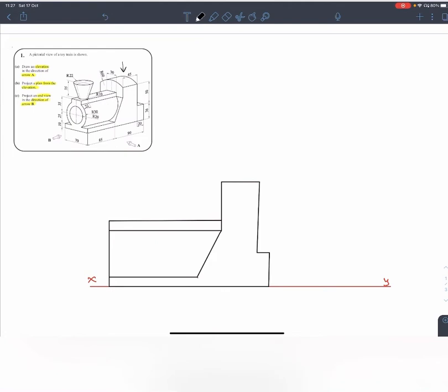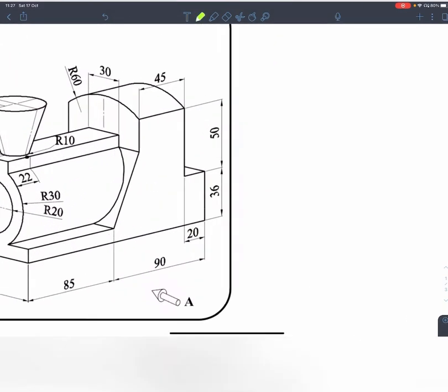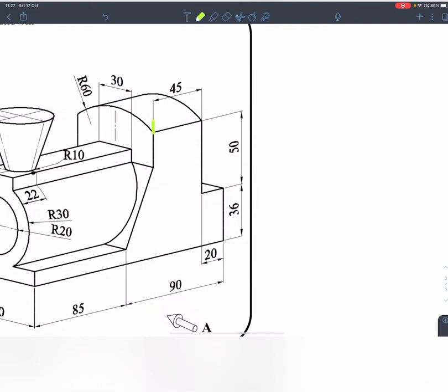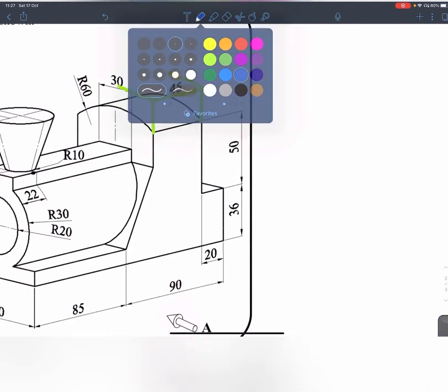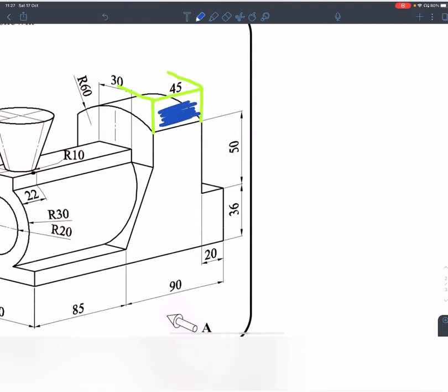So if we look at this section here, we see that it's curved around this way, right? But if we're looking in at it from A, if we follow our box like I've been showing you in the previous lessons, if we follow the box up, I'll do it in green, I'll zoom in here, right? If we follow the box up and around this way and down, the box should come along this way to meet the 30, right? So if I color in that surface, like I've been doing in the previous questions to show you, I will see a section here covered in blue.